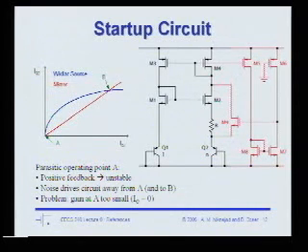So your point is, what if you want to reduce the headroom? Yeah, in fact, you don't have to use a cascode current mirror, right? The cascode is just used to give us a better supply independence. For PNP, I guess you have to, right? Because it's for same voltage. For this configuration, you have to use M1, M2.